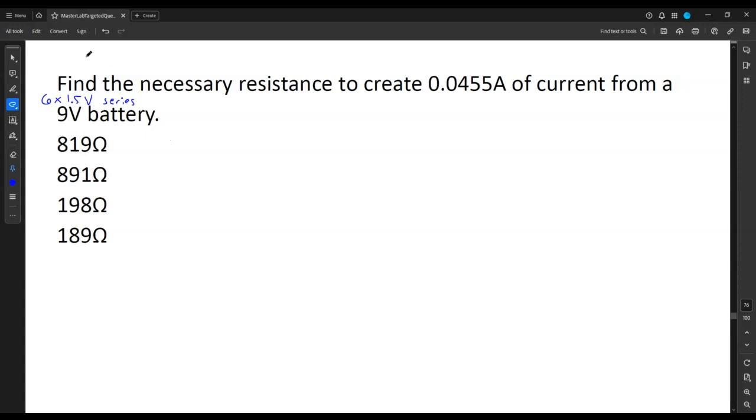So in a series orientation, what that's going to mean is, say you set up the batteries and you pay attention, you put positive, negative, positive, negative, positive, negative, like that, then they're going to add up and give more and more and more potential. So I guess I could draw the rest of the picture. I'm almost there. Positive, negative, positive, negative. Right? That's 6 pairs. So here's a battery, 3, 4, 5, 6. Yeah. So if these were all, say AA batteries in series, then that would make 9 volts total.